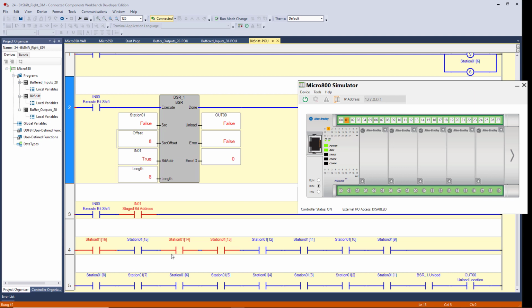So let's toggle these through. Think this through in advance. Where do you think that this is going to unload from? 10, 9, 8, 7, where do you think? So I'm going to turn off input 1. I'm going to start toggling. Okay, the leading edge is moving from 13 to 12, 12 to 11, 11 to 10, 10 to 9, still there. Let's see when the unload comes on.